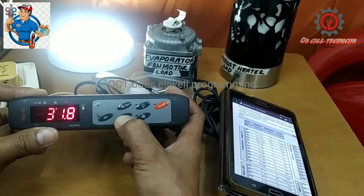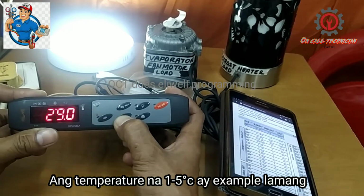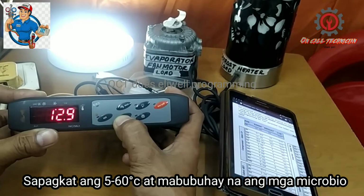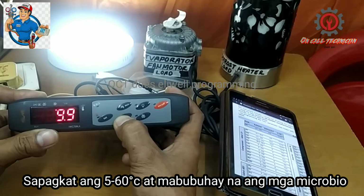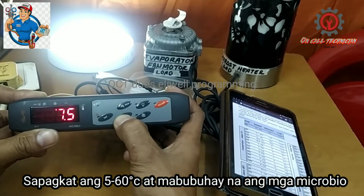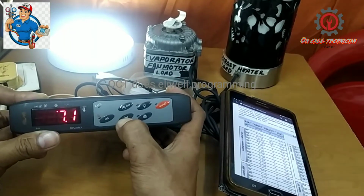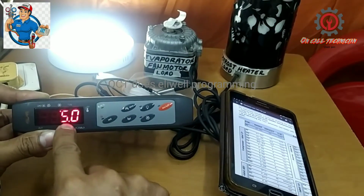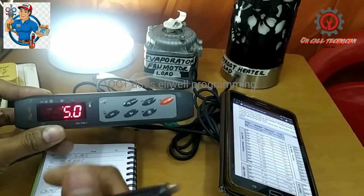Okay guys, the temperature I set here is just an example. Just follow what your company or your customer standard temperature. For example, that is a cake freezer and they only want positive 5 to positive 12, so just follow them. Okay, it's a case-to-case basis. Okay, here I put it to positive 5.